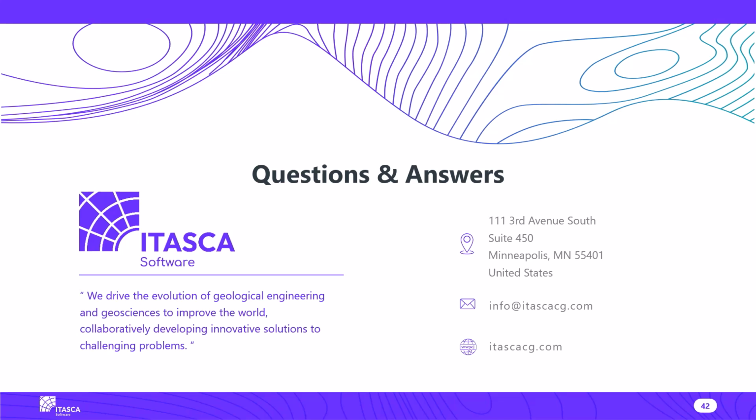Okay. So sorry, the very, very last one. Depends how fast I can read the question. Okay, so the inclusion of geological faults could reduce the zones modeled with hexahedral zones. Given this, would it be expected that FLAC3D's capabilities in terms of mixed discretization might be diminished? Not so sure I am getting the question. Well, I would presume you modeled this with a hybrid method where we have more tetrahedral zones along the faults, and then outside of that, it's presumably hex dominant or a pure hex model. Yeah, so correct. I think what they're asking is if the addition of those tetrahedral zones close to the faults might diminish the results with respect to mixed discretization.